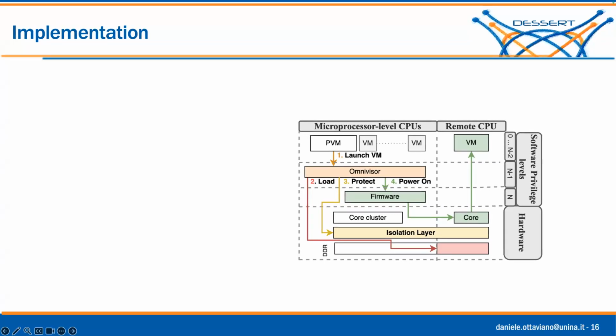So yes, on the RPU, there might be drivers for high-speed networks or control loops running on real-time operating systems. Okay, but it's not doing TCP/IP over a socket interface going back to the outside world. In one case, they are using lightweight IP without an OS directly on the RPU. Yeah, they've done that on the Ethernet machine.